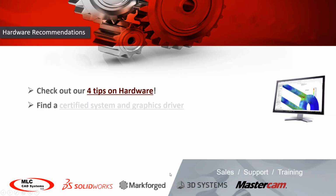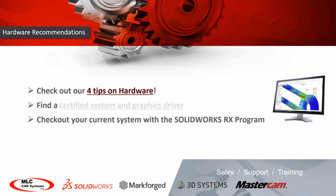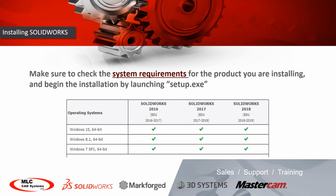I think it's really valuable to check out your graphics driver and which graphics card you're going to use with SolidWorks. If you've already installed SolidWorks, this is even easier through the SolidWorks RX program. This is one of the many efficiency tools that's going to be installed automatically with SolidWorks, so it will be in your start menus. Simply launch SolidWorks RX, click on the Diagnostics tab, and it will automatically look at your computer, tell you if there needs to be any hardware changes or settings changes, and it'll even recommend the best driver for your specific graphics setup.